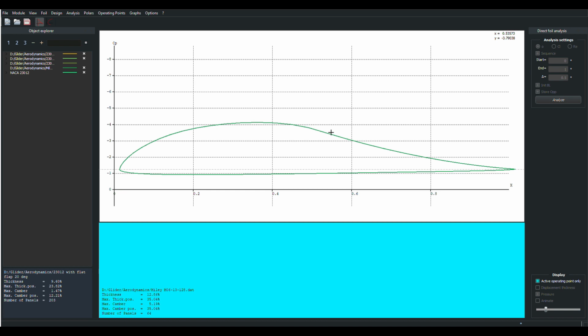And that's why over in Europe, when you fly the Aerooptrix against the Swift, on light days the Swift wins because it's a good floater, and the Aerooptrix wins on heavy days because the Swift can't really speed up and catch up or stay up with the Aerooptrix, because it's got all the drag coming off from this rapid pressure recovery region. So everything's a compromise, and so this is why I didn't put a low Reynolds number airfoil on my wing.